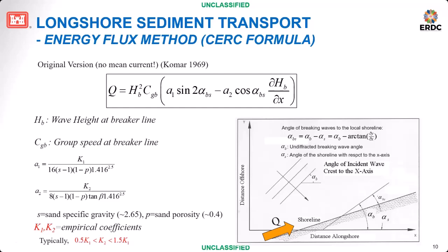I cannot emphasize enough that you have to do the validation and calibration. But the calibration parameter is not so much about longshore sediment transport, but more about the setup of your structures. I will talk about that later.